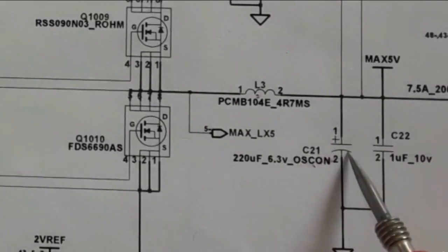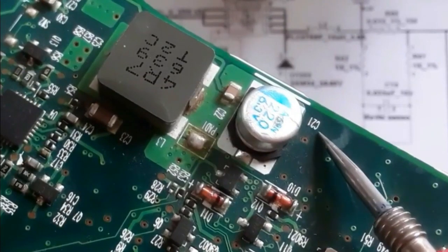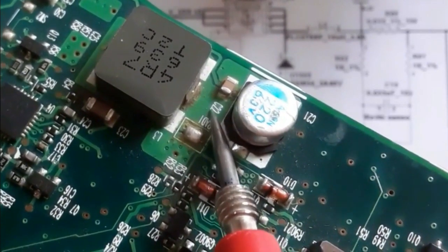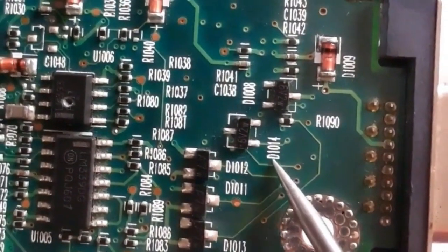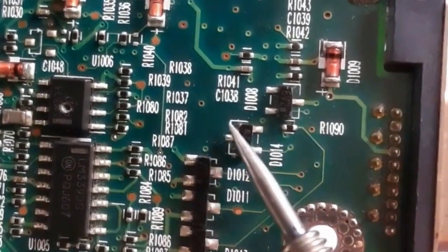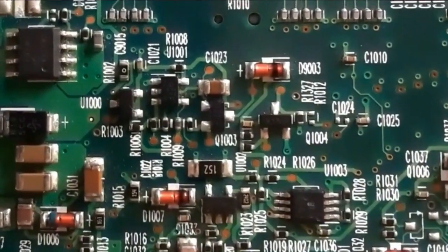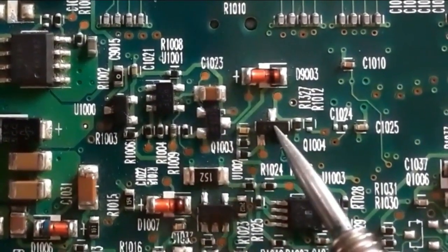C21 is a polarized capacitor, a chemical capacitor, and this is a ceramic capacitor on the motherboard. But for this C22, this is a ceramic capacitor. They have the same shape, as you can see. This is a diode, we have D, and here, as you can see, the same component, but we have the reference